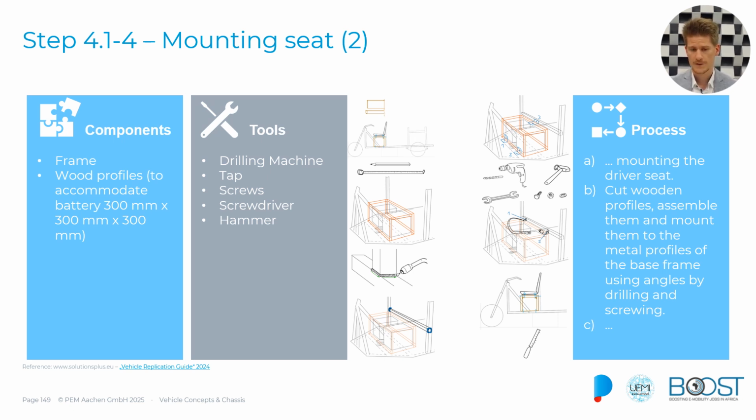The wooden profiles depend a little bit on what you want to have. There should be something like a section of probably 40 by 40 millimeters at least, and it should be properly screwed and probably bonded adhesively as well.